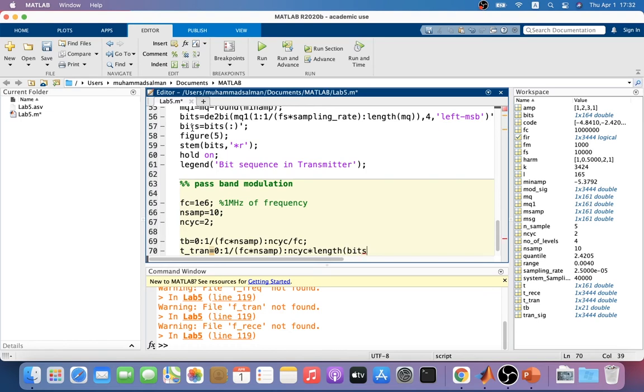So the length of bit means the size of that bit, and then I will make it the numerator and divide by what is my denominator, divide by Fc, because it is starting from 0 and same as this one, but instead of 2 cycles, now I have this many bits. Each bit has to be conveyed by 2 cycles, so that's why I have to divide by 2, which means that each 2 cycles of 2 microseconds should be conveying one bit, right?